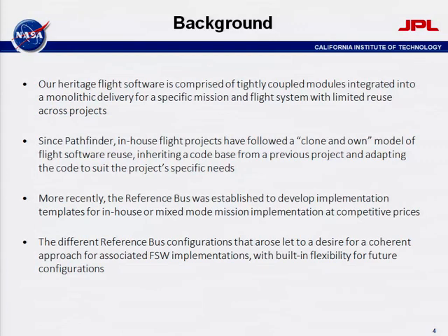Recently, there has been an effort within Division 34, our avionics division, to create something called a reference bus, which is basically a standard set of hardware boards and pieces of hardware that are meant to be the catalog from which a project develops the deployment environment for the flight software on the next mission. So for a particular flight system, you go to this reference bus and you can pick out which boards, which computer, and what kind of configuration you want.